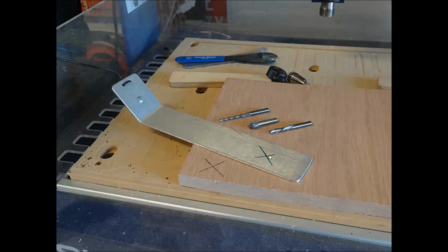I have an X on my plate, and I try to get it within a quarter of an inch, the same thing every time. So every time I change a bit, I use the keypad, move it over above that X, put the next bit in, hold the Z0 plate approximately right over that spot, and that really does help, especially in cuts where you want to have multiple bits at the same depth and you need to line them back up.